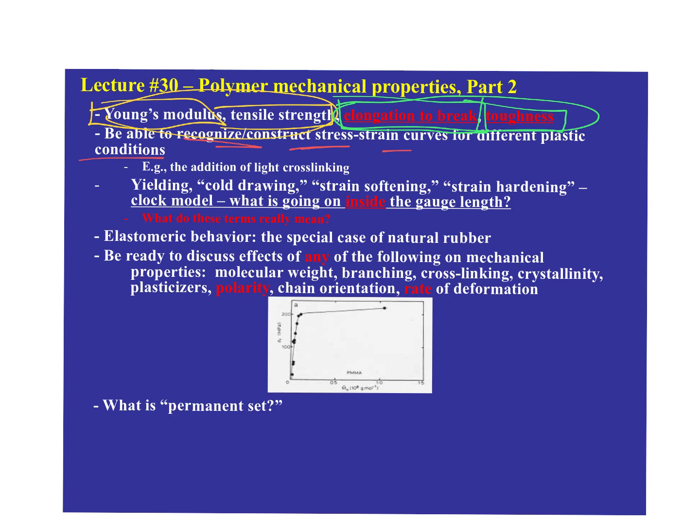How is that going to be dramatically changed by the addition of even just light cross-linking, which will certainly make a huge difference. You should be able to see why that's so important. For one, flow down a tube becomes really, really hard if you have even a small amount of cross-linking, because all those polymer layers can't shear by each other anymore, for example. Okay? Any questions about that?